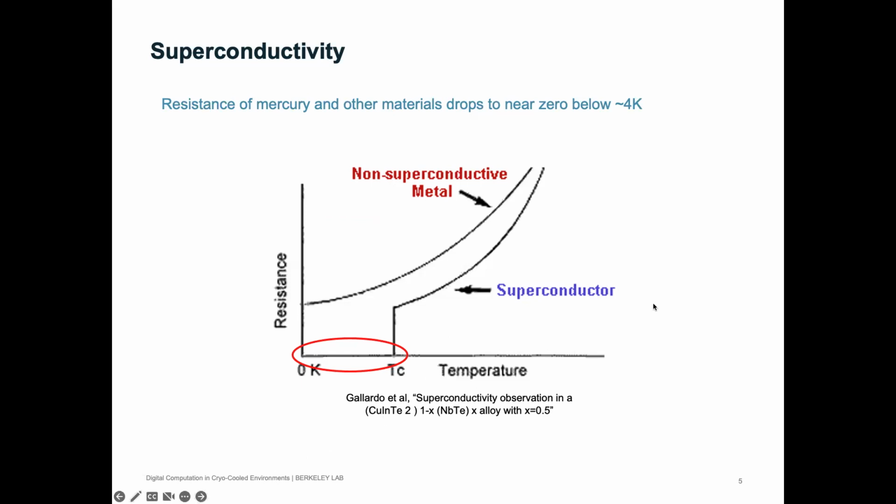Now, this is not just take a chip and freeze it. The underlying technology in what I'm talking about is also a lot different. We don't have the transistors we're used to seeing. We have these other devices called Josephson junctions. There's a lot of physics going on here, but I'm going to abstract it. At a high level, a Josephson junction is basically a device that has two superconducting ends separated by an insulating barrier.